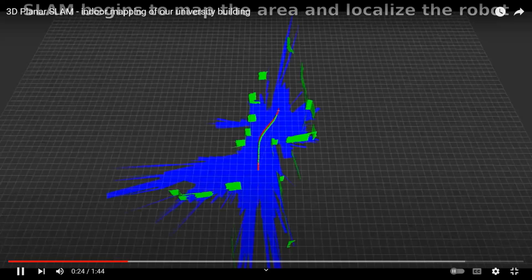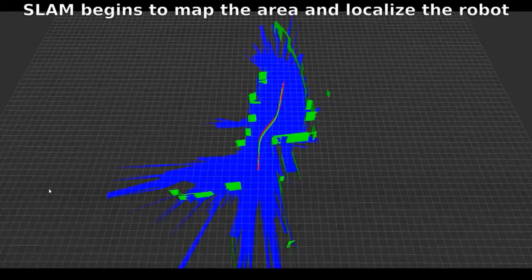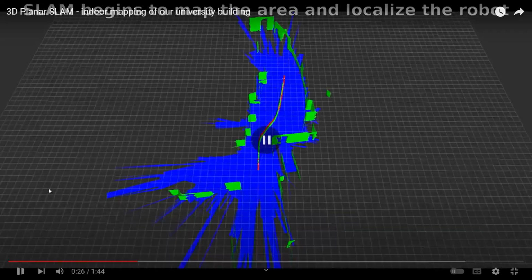So this is actually the green one. If you all remember, I said earlier, there's this odometric mapping, right? Field odometry. Based on the encoder positions, you can basically map the robot's trajectory, and also you can map based on the sensors. The green path is estimated by the Kalman filter. They are doing the mapping, and at the same time, you can see the odometric trajectory in red, right? You can see the difference.